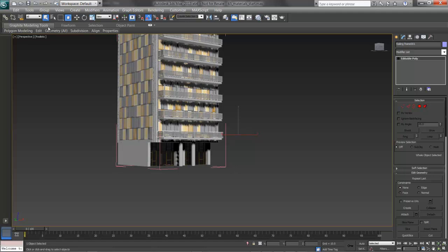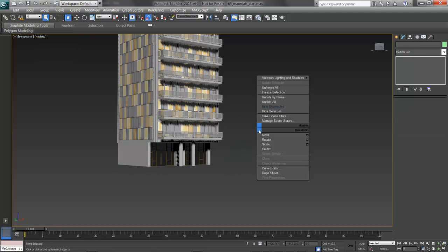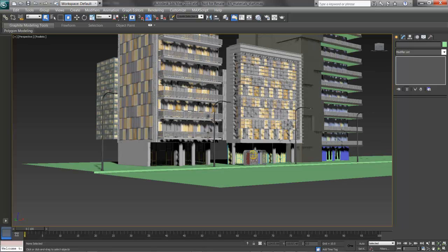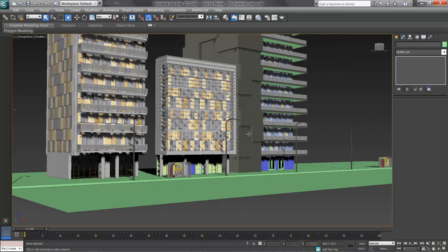Once you're done, close up the group, choosing Group, Close, and Unhide All. That's a right click, and there it is in the display quad. With everything unhidden, that building is looking better, and I'm on to the next one. In the next video then, once I go through and get all the materials squared away in their solid colors, I'll look at adding in textures. As we can see here, I've used some already. We'll put a texture on the road and concrete on the sidewalk.